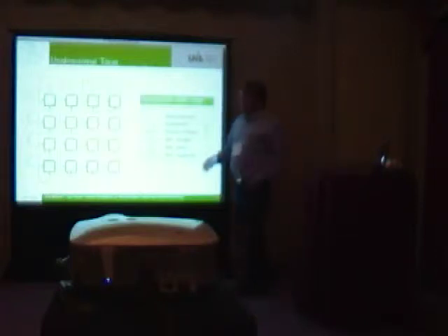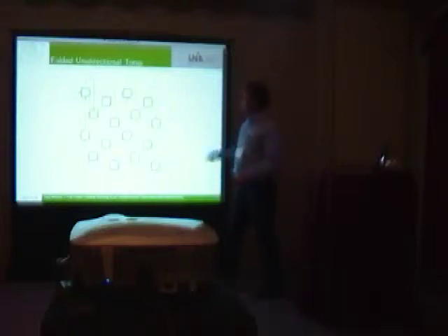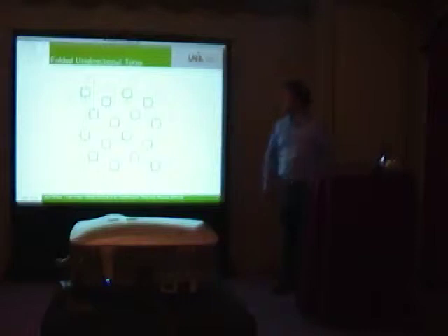One problem for the clock frequency is this long wraparound link. But you can solve this by rearranging the network, which is then called folded, and so you have here always links that are double the size of those in a mesh, but they all have the same length. So to avoid this wraparound.